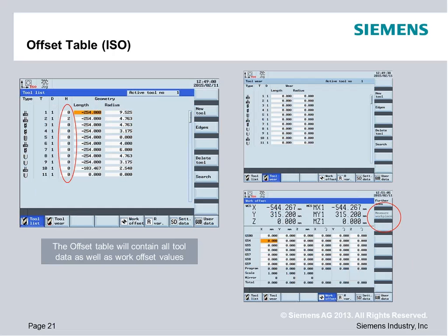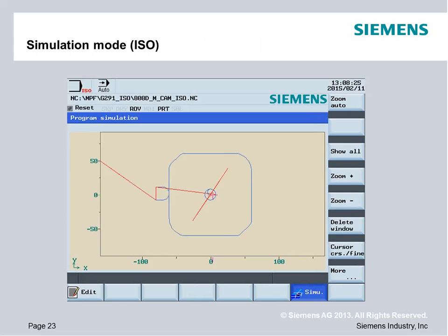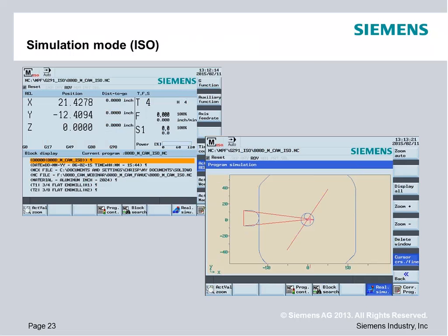Okay, so we're at 7 minutes, 48 seconds if memory serves me. So what would happen if I was to go into the program and change this Cycle832 right here? I was just staying away by a certain amount. I think I left 20, 30 thou on the surface. So now if I looked at it, I was tightening up my tolerance, and I was down here in my semi-finishing. My two lower diamonds were triggered. And then from there, I went down to the full finish. This is where I was really concerned about my dimensioning.